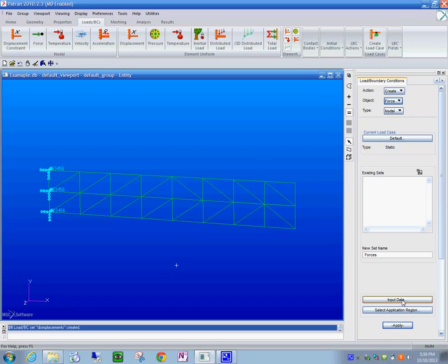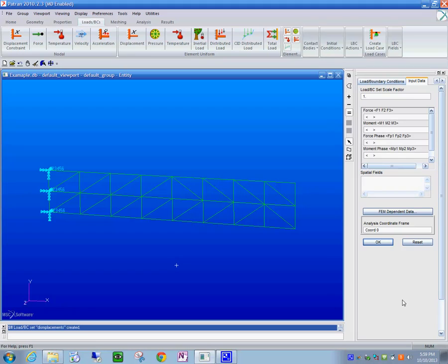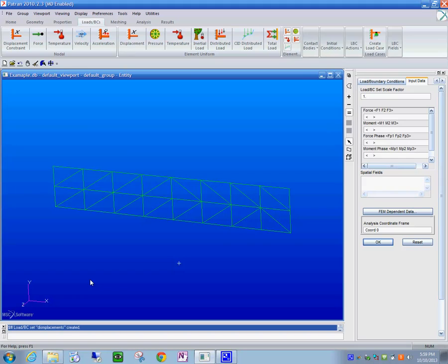Then same procedure, it needs the input data. If we want to put the loads over here, then it makes sense to specify that the loads are going to be in the minus y direction, right? I'm just making that a little bit larger so that you'll see it well. So this would be a 0. Then we have a minus, let's do 1000, and then 0 again.